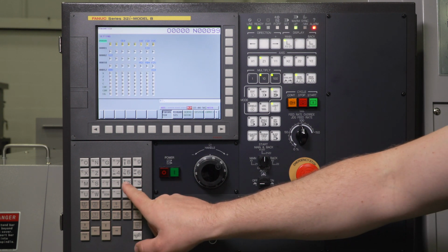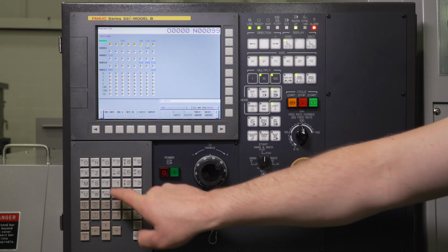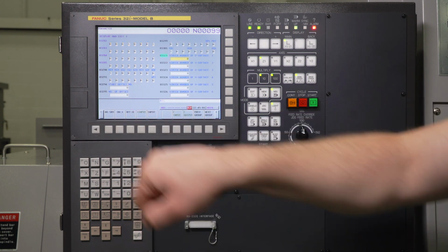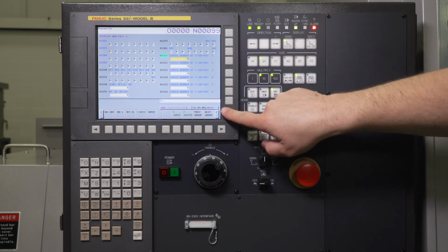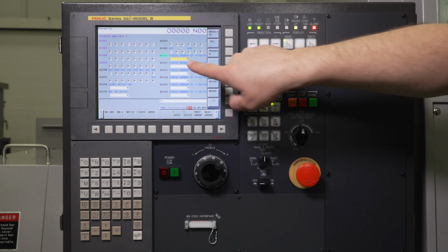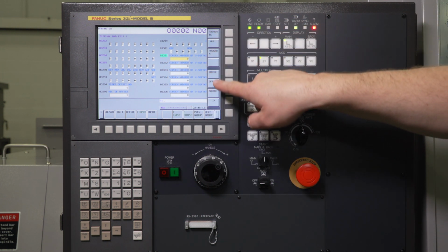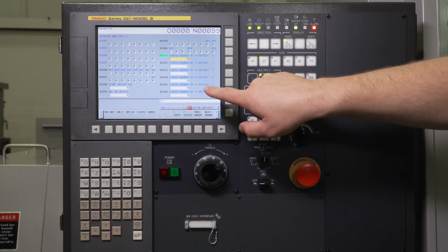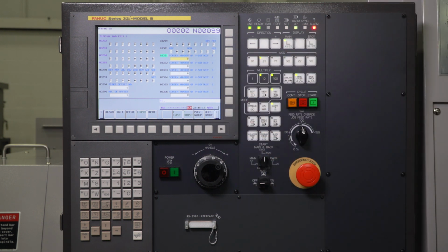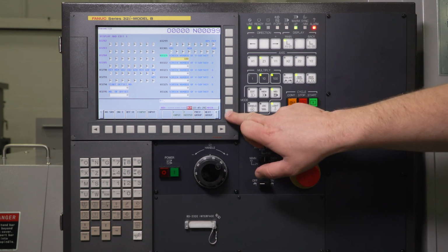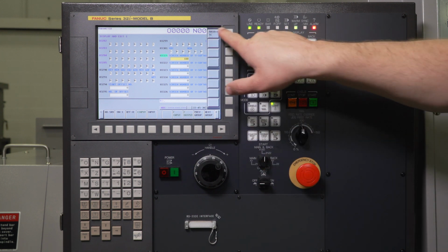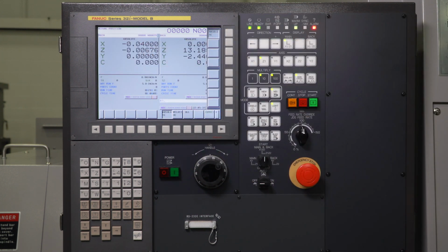So we're going to go to parameter 3321, and then press number search. This brings us to the screen number of vertical soft key 1. That would be this one. Each parameter in sequential order is going to represent one of these keys. So for number 1, we're going to put in a 100. And screen 100 is absolute position. So if I press 100 and input, and now when I press this, absolute, it's going to bring me right to my absolute screen.